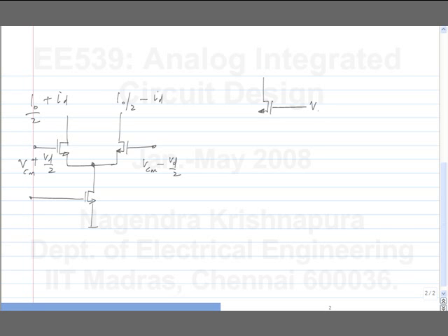This is biased at some fixed voltage, or incrementally it is grounded, and there is a certain bias current flowing through the transistor. Okay. And I apply a signal current here. Now that signal current comes out with a gain of 1. Okay. If the source that is pushing I signal has a certain impedance RS, from here it looks like a much higher impedance. Okay. That's what the common gate amplifier does.